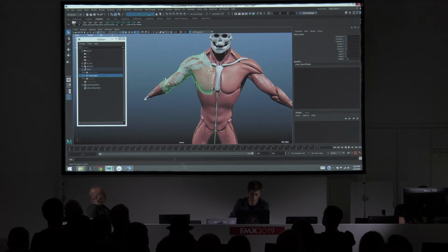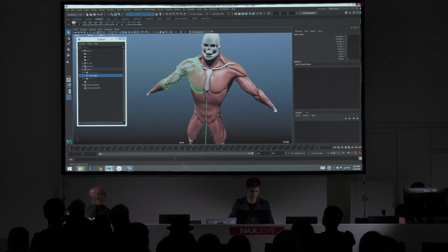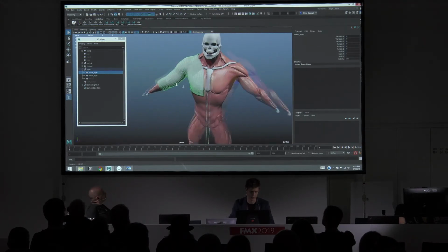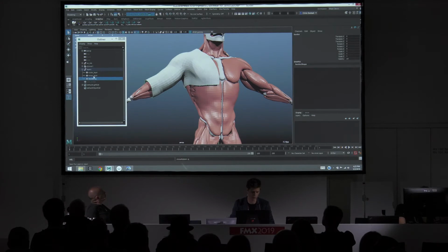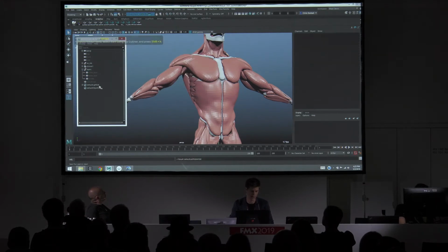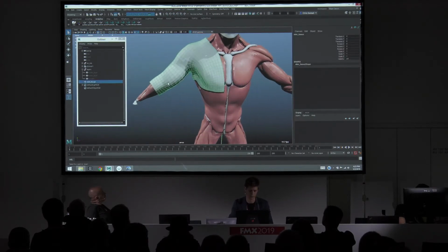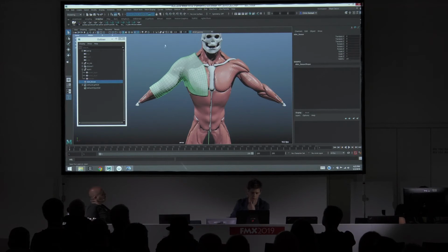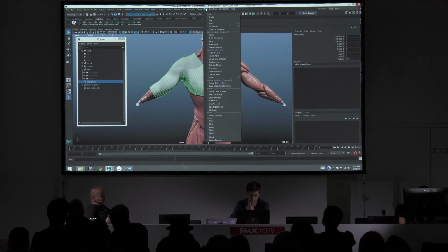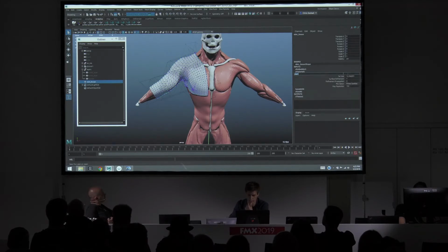I actually used our cloth solver to help model this. If we have time, I can show that, but maybe not. And then you have an outer layer, and I've just built a border between these two. Then you combine it all, merge the vertices, conform the normals, and you end up with a closed volume that you can run collisions and things against. So I can convert this to a Ziva tissue object now, add simulation component tissue. I'm going to change the tet size to something like 4.